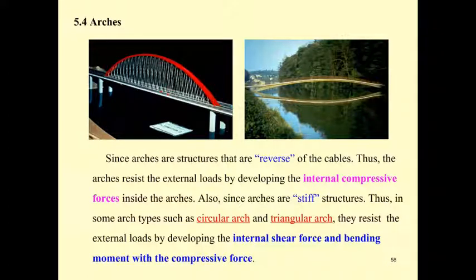The cable that we are studying is the statically determinate cable. That means we can analyze the cable by using the method of sections and method of joints to obtain the reaction and the force in the cable. The cable will have the maximum tension force in itself, and most of the time the maximum force occurs when the cable has the maximum angle with the horizontal line.